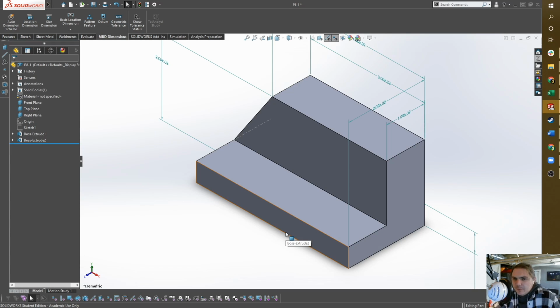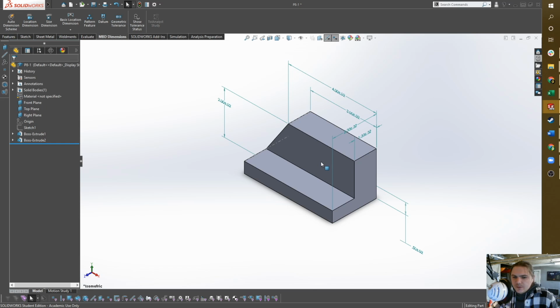I'm going to assign you a couple parts that I want you to demonstrate the SL of SLOPF: size, location, orientation, form. So we'll just be focusing on size and location. You're going to use DimXpert and just the location and size dimensions to fully define a part.